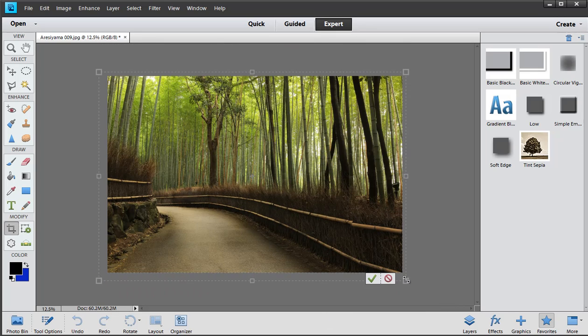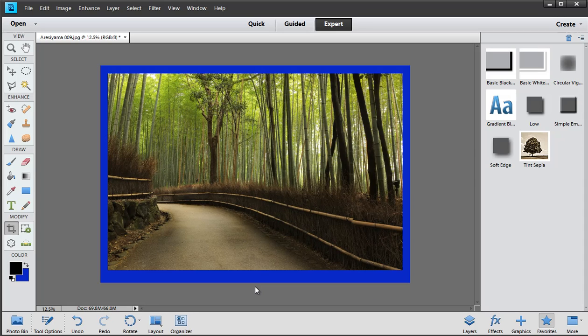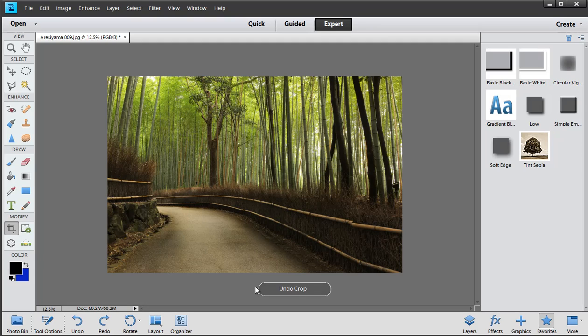This tool option thing popping out just drives me bonkers. There we go. And we just get an equidistant border on the top, something like that. Probably need to pull this down the screen a little bit like that, and then press enter, and there's my blue background. So choose the color first, by all means, then go off and create that border. All right, second way of doing it is probably a lot easier.